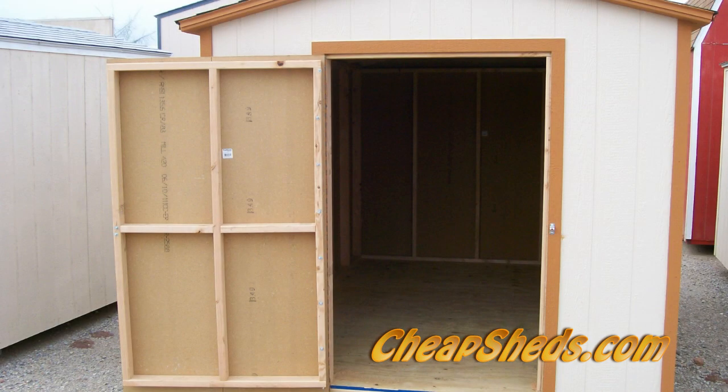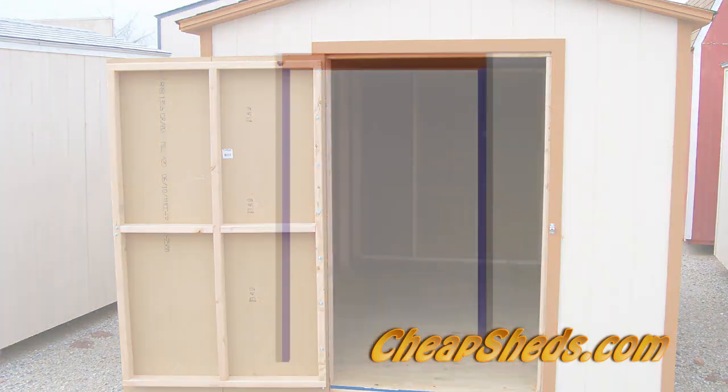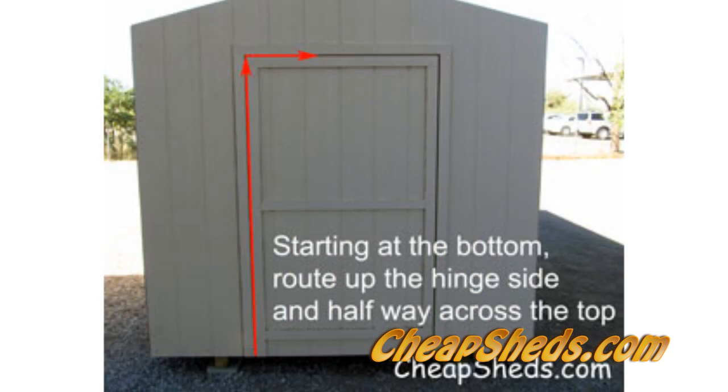This door construction method saves time and money because it uses the materials that are cut out of the rough opening that would otherwise be thrown away. It consists of an outer frame which is built into the shed wall and an inner frame which is the actual door. These two are framed and sheeted at the same time. Then in step 7 you'll cut the door out and install the hinges and latch.